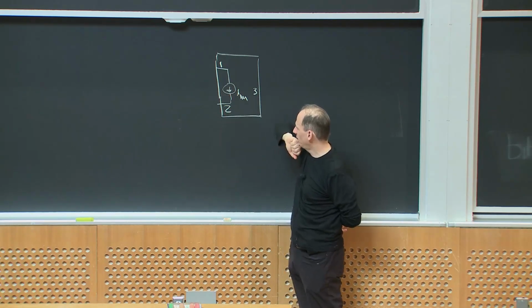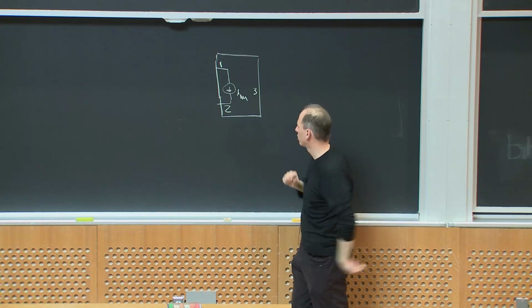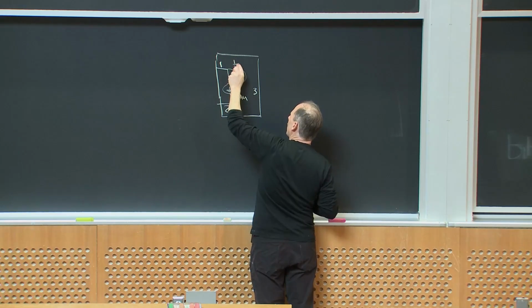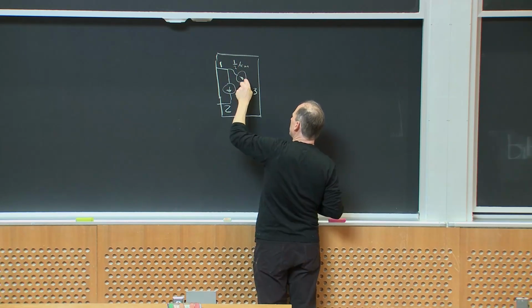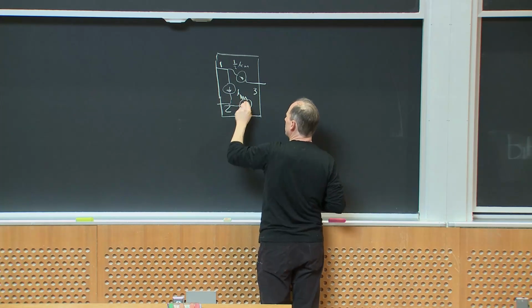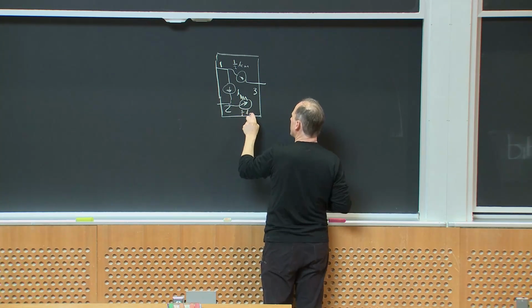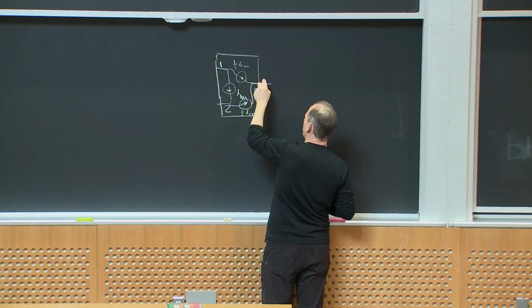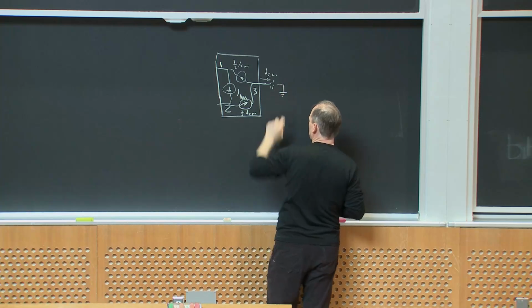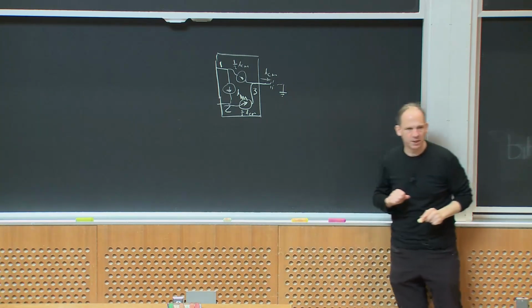And then if I thought, well, I might be driving some common mode currents, what would that be? I'd have 1/2 ICM being drawn this way out here, and 1/2 ICM being drawn this way to the output, and then this would be ICM to ground through my parasitic capacitance back to ground. Does that make sense to everybody?